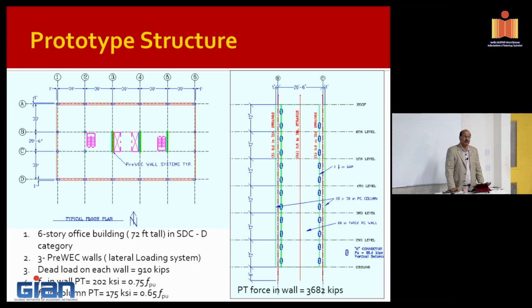What you should be looking for is, just like you do for cast in place, you will calculate the seismic requirements, which is basically the equivalent of how much total load one should resist for that particular structure, or one should design for the building to resist.